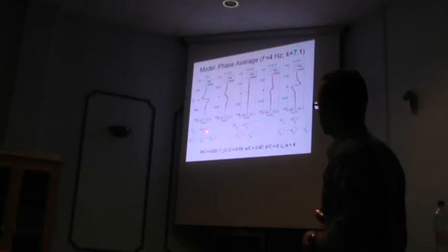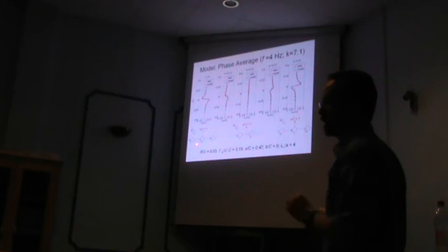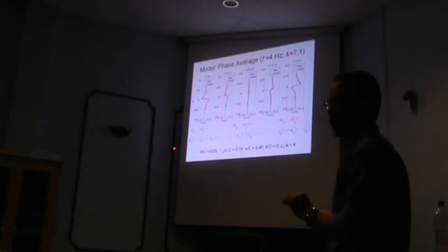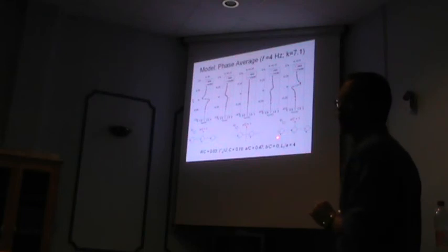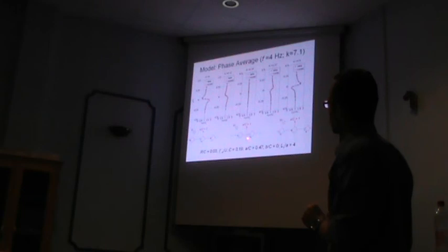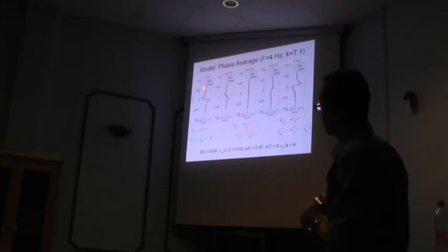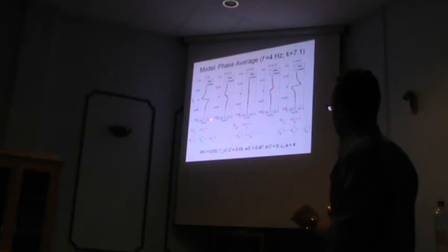You can see that at phi equals 0, the positive vortex is located at the location where we're doing the calculation. At phi equals 0.5, the negative vortex is located at that position, and at 0.25, it's halfway in between. The graph here shows this bracketed U, the phase average velocity, which is the velocity at that particular phase of the cycle. The solid line is our model, and the red symbols are the experimental data.